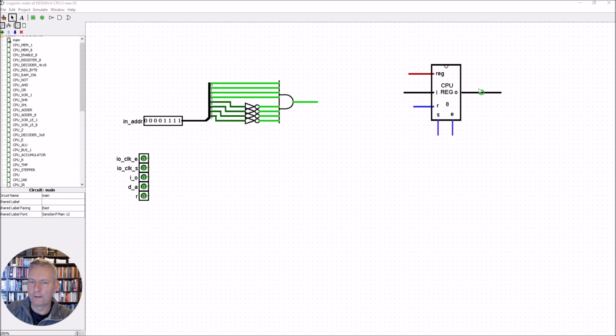So let's say we want to input the data into the CPU. Now, if we're inputting data into the CPU, we're going to be outputting it from this device. That is, we're going to put information onto the bus from this device. For example, we're typing on our keyboard, and at some point we're going to click the enable, and it's going to enable that information out of the keyboard onto the bus and into the CPU. We're going to do that whenever our IO goes to 0 and our data enable goes to 0. If you check the little truth table, you'll see that those are the 2 bits.